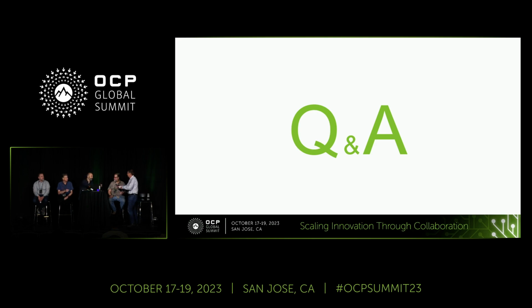I will say that the Gen 6 by 1 also has some assumptions on what you have on root port capability. That's a capability that we could try and drive in the industry to support. I do agree with Lee from a cutting edge perspective and making sure that you amortize cost, and whether Gen 5 by 2 is good enough as a way to get some lane consolidation. That's already supported today in almost every root port, to be able to bifurcate down.